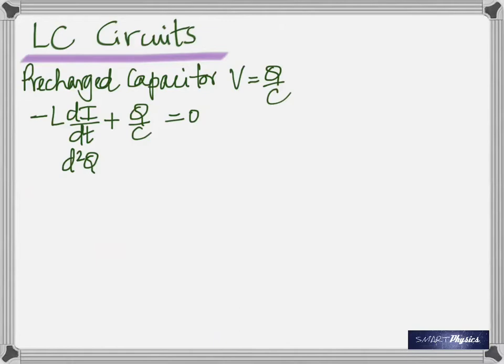it's going to recharge the capacitor in the opposite direction. What do I mean? So if this plate was positive, this was negative, now it's going to get charged the other way around. Are you seeing this? And then after the whole magnetic field in the inductance coil collapses, the capacitor's back to maximum charge and the process continues. Now let me ask you, can you see an oscillation here? It's called an electrical oscillation, just comparable to the mechanical oscillation there.